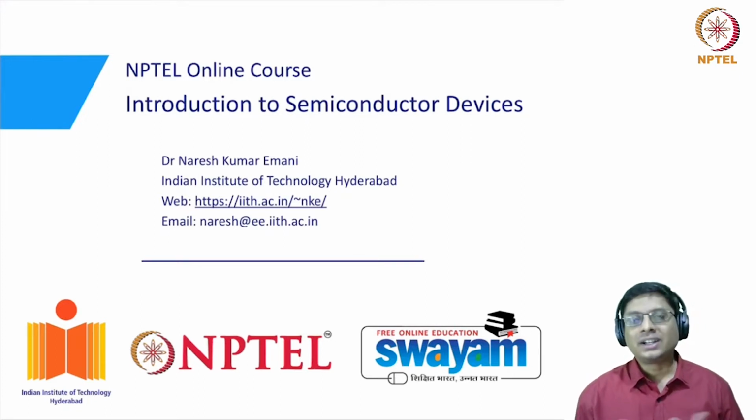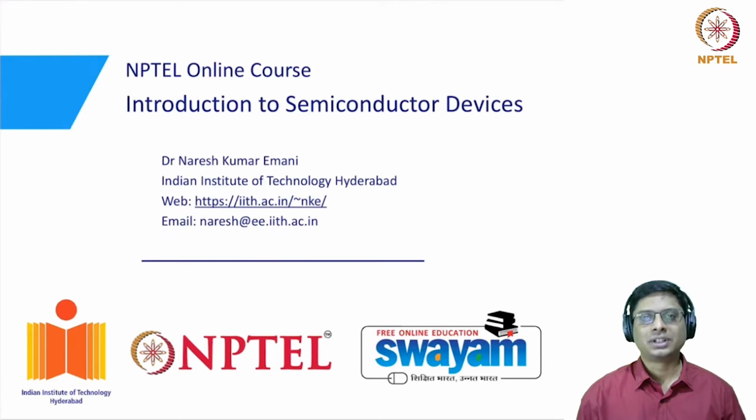So is there any capacitance associated with the diode? That is what we would like to answer. Why are we interested in capacitance? Well, it turns out that the product of resistance and capacitance is one of the most critical parameters in the operation of electronic circuits. You must have studied in the basic circuits course, the product of R and C represents the delay, right? RC delays we call them. So if the product of R and C is large, the electronics cannot work at a very fast speed.